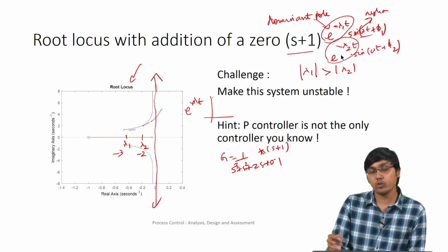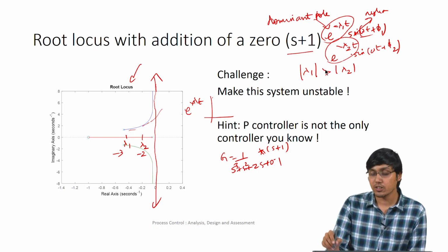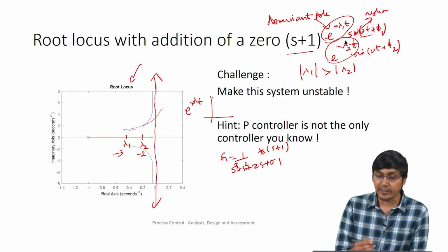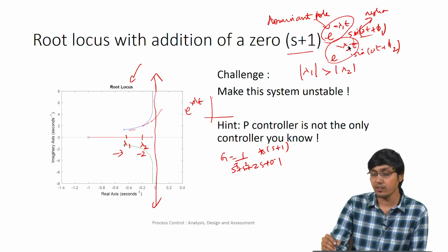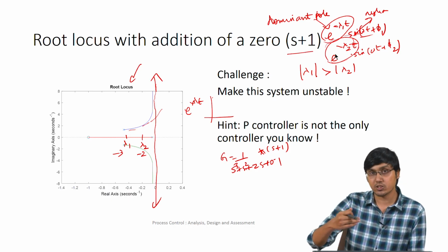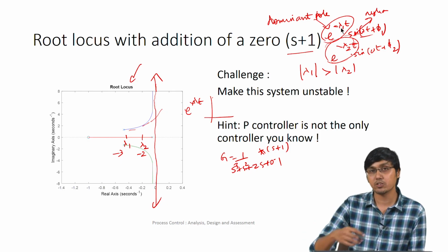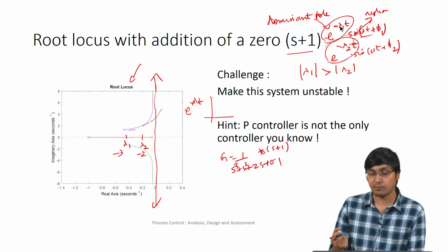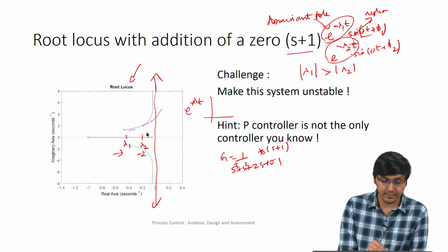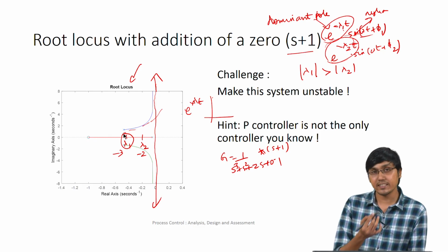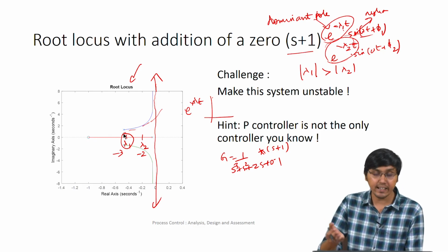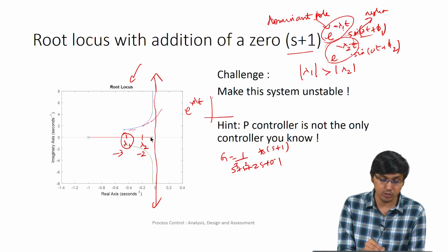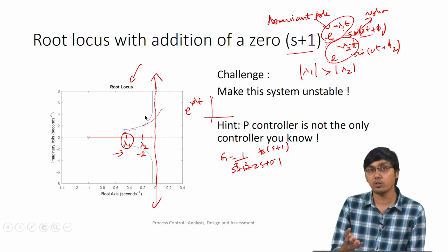You can plot these two values for the same time and see in MATLAB how the system is responding. That is one way to do it, but we can easily see by intuition that this particular term is going to decrease slower, and this particular term is going to fall faster because lambda 1 is greater than lambda 2. So this pole is not causing a bigger impact in comparison to lambda 2. So lambda 2 is a dominant pole compared to lambda 1.